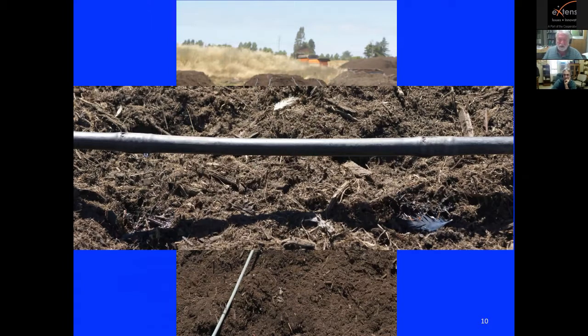This pipe comes on long reels, and you can just lay it down. With 4 lines, you're applying about 4 to 5 gallons per hour for every foot of that pipe that you put out. So at 200 feet long, like the windrow was, that's 3,200 to 4,000 gallons that you're adding. That means you've got to have a supply line that can add 4,000 gallons in a reasonable period of time, for instance, 6 or 8 hours. It takes 4 to 5 hours for water to go from that irrigation pipe to work its way down through the pile to get down as far as the bottom of the pile. So we're going to have, you know, a quarter of a day for water doing what we call redistribution.